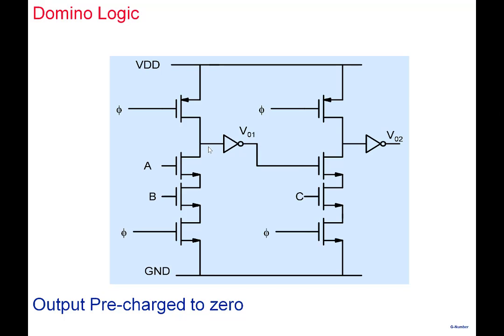Because, okay, if it pre-charges to 1, so let's say this is 1, 1, 1 here, and we apply a 0. We apply 0 here, clock is 0. So this particular node charges to 1, and this goes to 0. Okay? Now the correct value is not 1. The correct value is 0 here, and the correct value is 1 here. So it may take time, but note that because it's 0, when you apply a 1 and 1 here, fine, it will take some time to drop to 0. It will take some time to go from 0 to 1, but it's not causing any error in this. Why? Because 0 is a non-enabling input to the NMOS transistor here. It's not causing any error here.